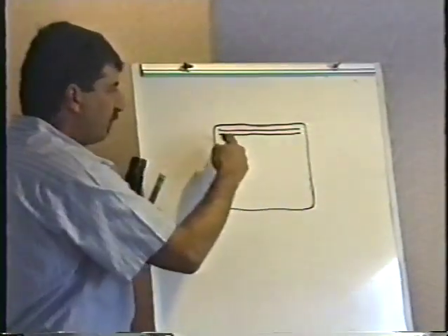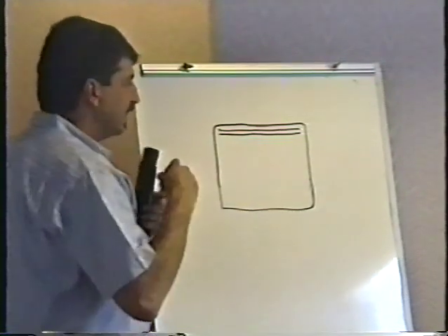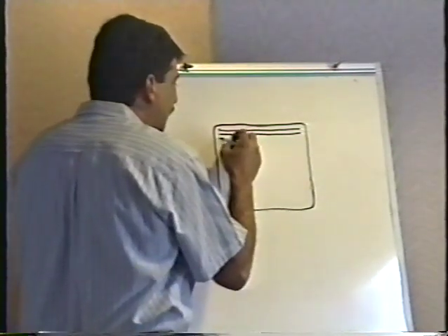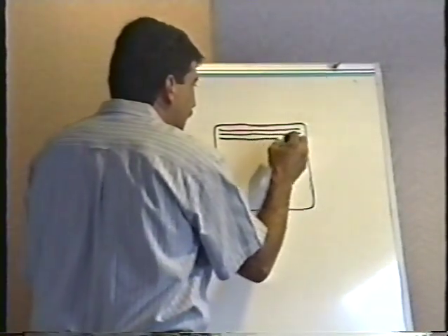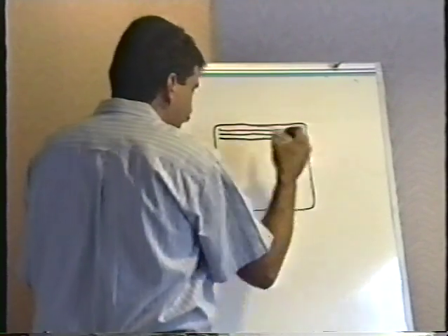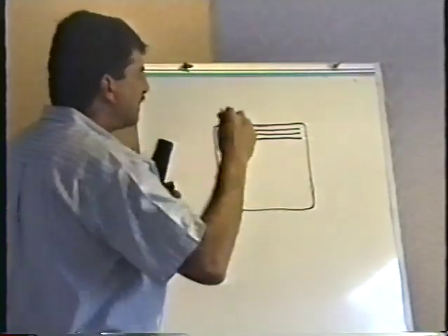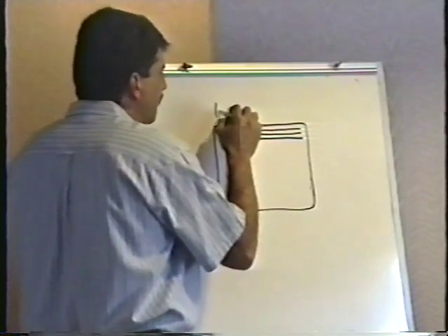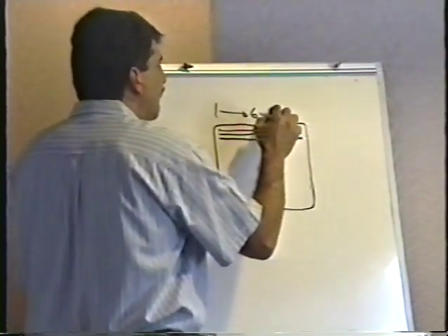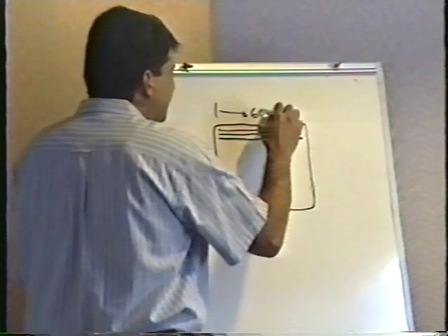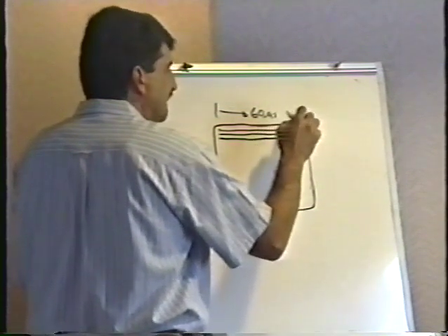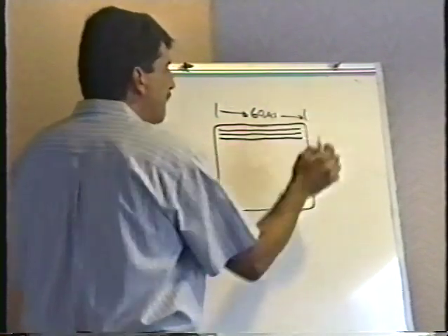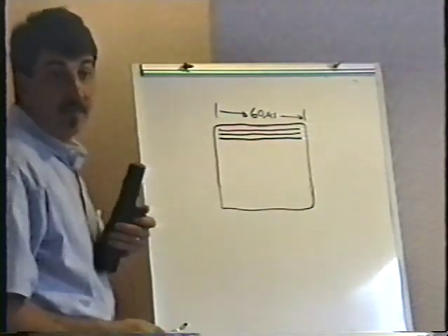The magnetic field resets to start the beam back at the left-hand side again, and it draws a line from left to right. You don't really have to know this, but it takes approximately 60 millionths of a second, 60 microseconds, for the beam to move from the right side of the screen back to the left side.